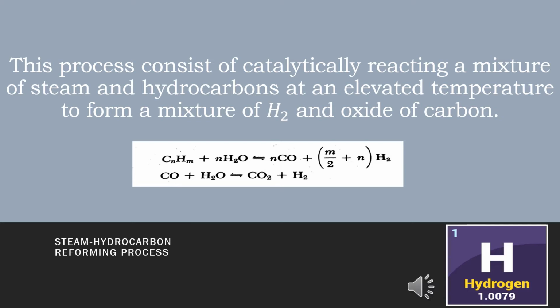This first reaction is the reforming reaction. It is highly endothermic and the moles of product exceed the moles of the reactant, so the reaction goes to completion at high temperature and low pressure. Excess steam is normally used. Although the basic purpose is to prevent carbon formation, it also helps force the reaction to completion.